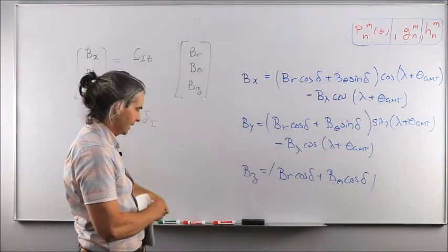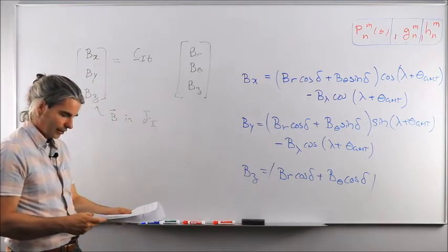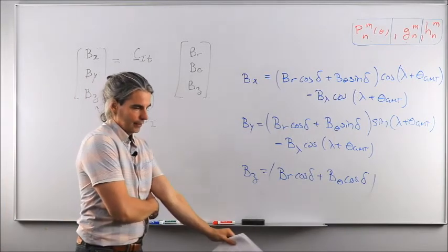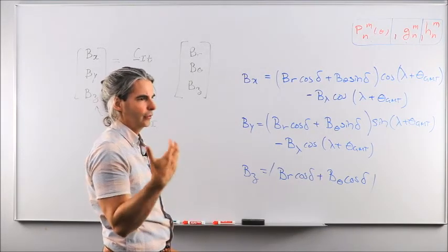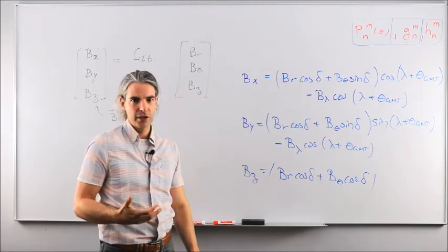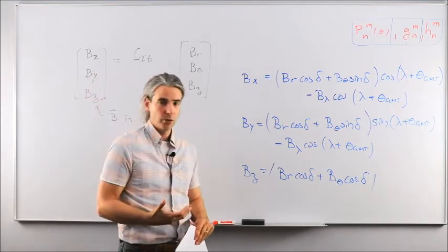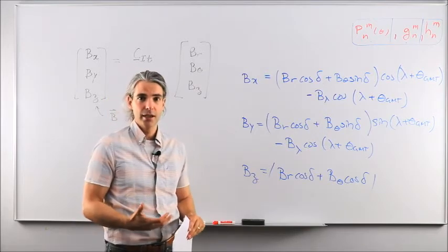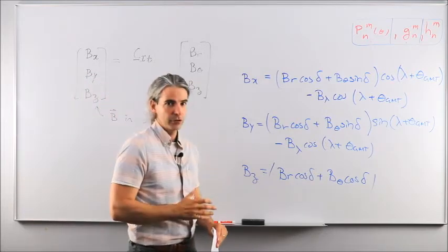That gives us the magnetic field vector expressed in terms of its x, y, z components in ECI, Earth-centered inertial, but that's not really what we want, right? Because I said that we wanted to have the field in the body fixed frame such that we could then take the magnetic dipole of the spacecraft M, expressed in terms of the body fixed reference frame, and then be able to take the cross product, or because now we're talking about components, take the skew symmetric and obtain the perturbing torque in the body fixed reference frame, okay?